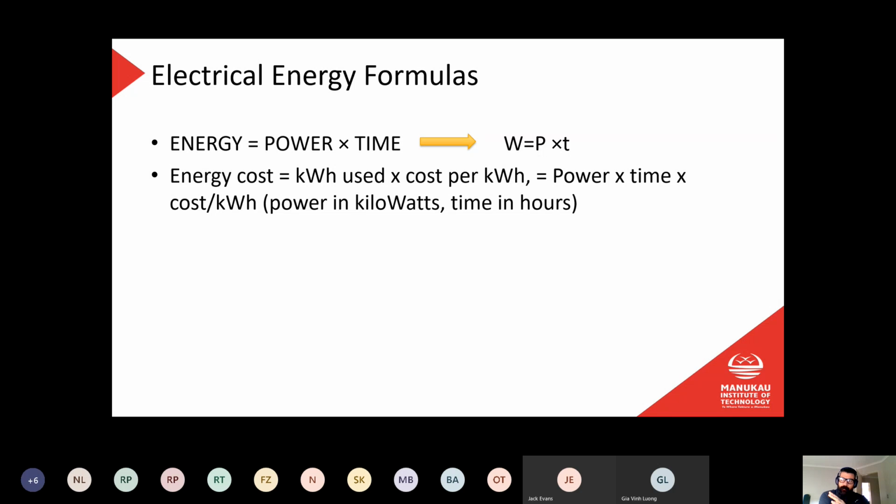It's always got to be in kilowatt hours, because, like I said, a kilowatt itself is not a defined unit of energy. It's just a rate of using energy. So without telling me the number of hours, the kilowatt means nothing. When we measure our electricity costs, it's always in kilowatt hours, and that's the amount of kilowatts we're using times the time. So if I use 2 kilowatts for 1 hour, that's 2 kilowatt hours. If I use 1 kilowatt for 2 hours, that's also 2 kilowatt hours. And our price of electricity is always given in a dollar value per kilowatt hour.